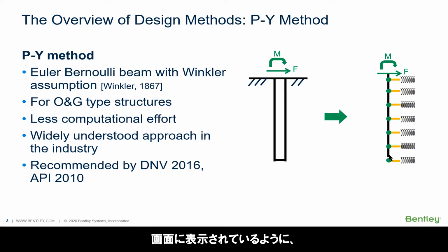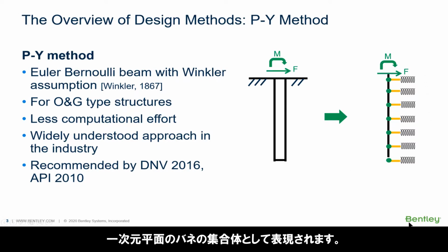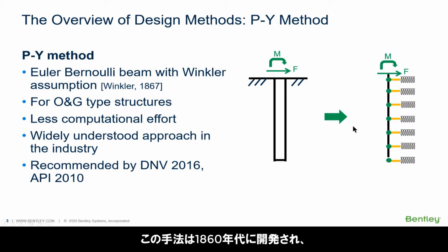Local soil reactions are represented by a bunch of springs in a one-dimensional plane. This approach was developed in the 1960s to mainly prevent the collapse of fixed jacket-type structures and has long been used in the offshore oil and gas industry.